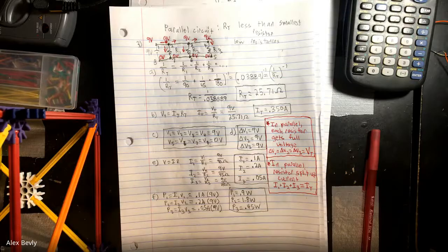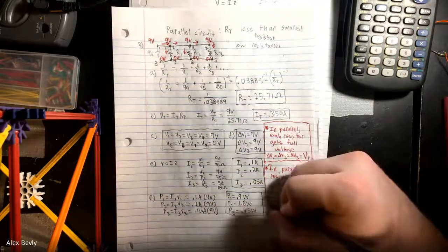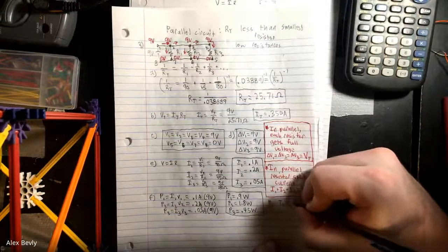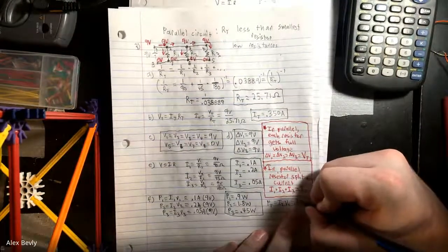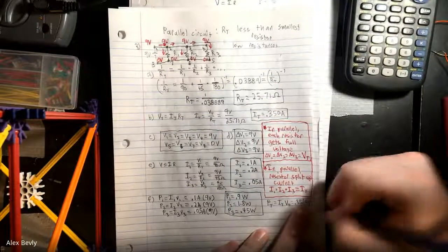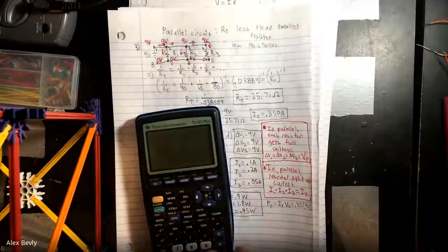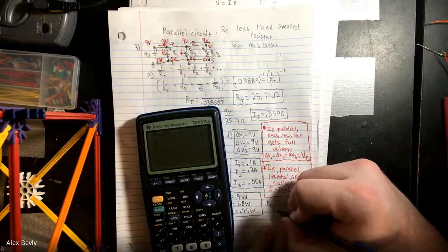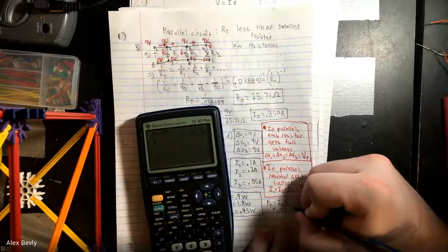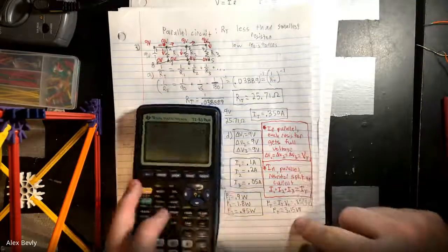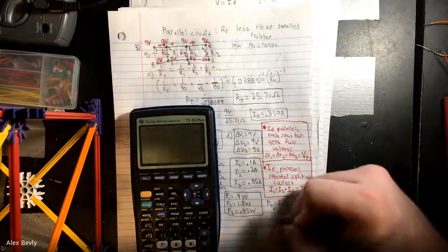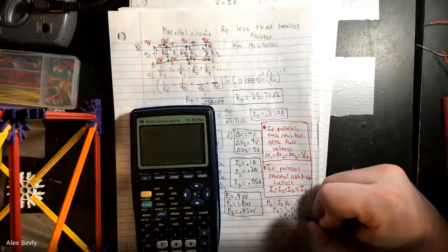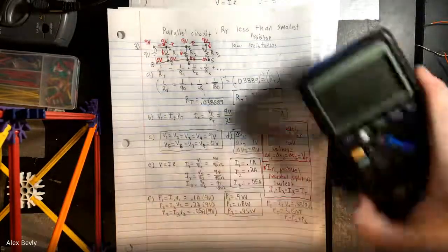And we could go through and get the total power for the circuit. So total power would be total current times total voltage. So 0.35 times 9 volts. 9 times 0.35, we get a total power of 3.15 watts, which we'll see is the same as just adding these up. So this is going to be identical to just power 1 plus power 2 plus power 3. So powers, you're always just adding them up.